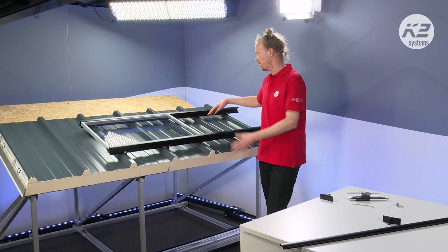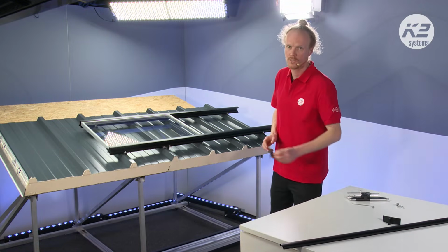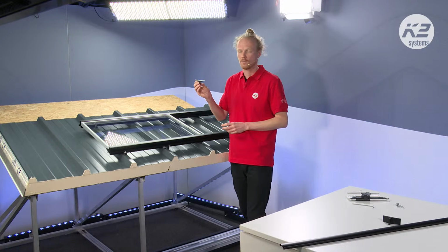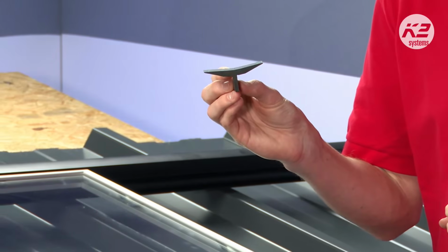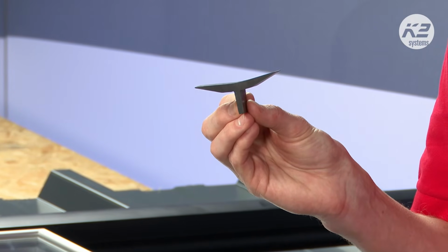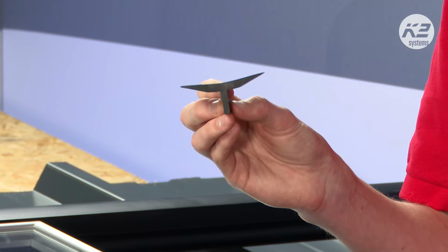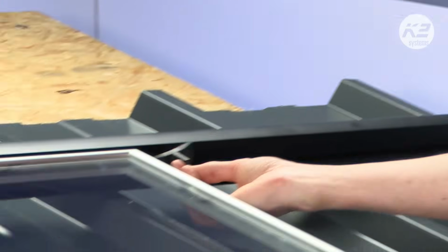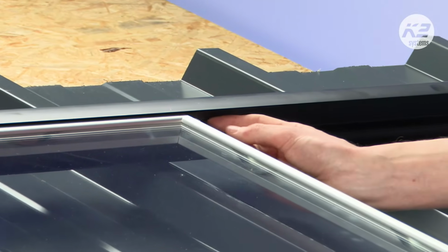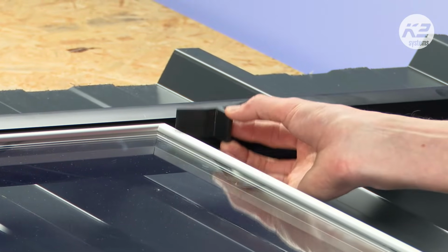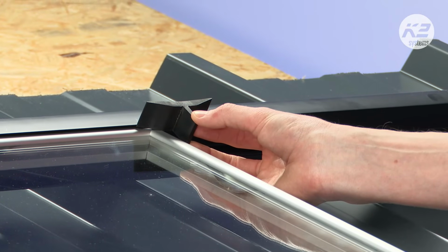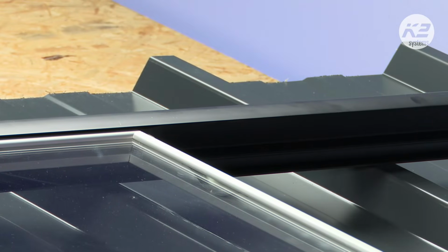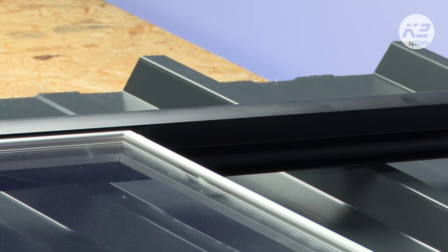We then want to put, for example, our second panel in. We're going to ensure that there is a little gap between the panels, and we also will now ensure that the panels cannot be taken out. And we do this by putting the module safety in, right? So this ensures that there is a 5 millimeter section between the panels, and it's just going to sit up. It's effectively not seen. It's just going to sit up into the panel, into the rail, sorry. And it does two things, and I'll show you those two after I've put this in.